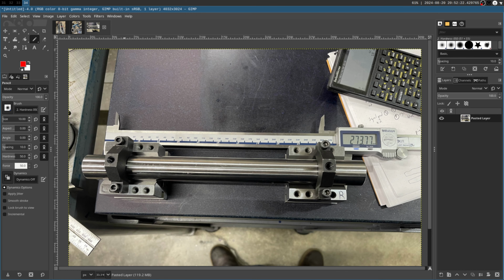So the bed and everything will always be parallel. It is the contact feet of the headstock that will be changed, which makes sense because that is a very fine-tuning thing. You want to have just your small contact points that you're adjusting. You can't change the plane of the bed constantly to make those things work. Well, also it's just another fixture that you're attaching.